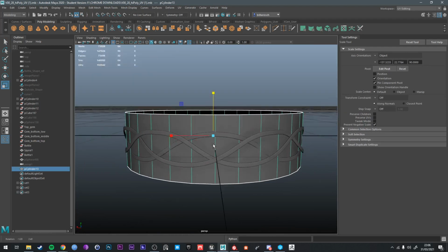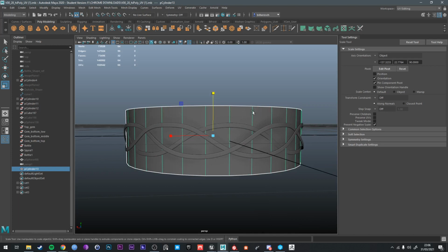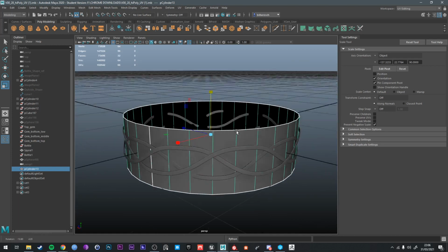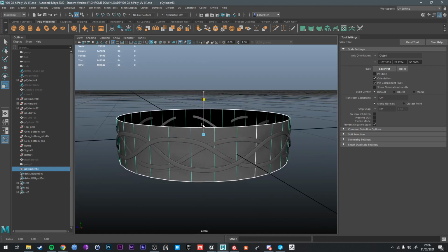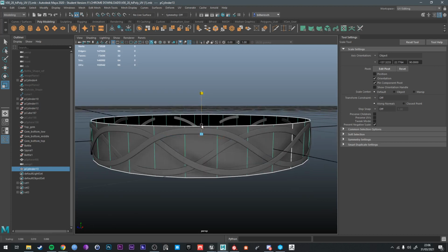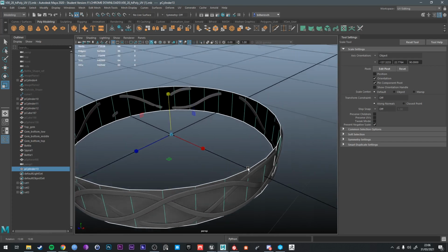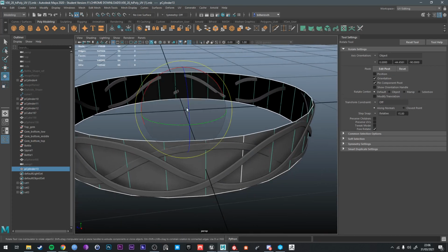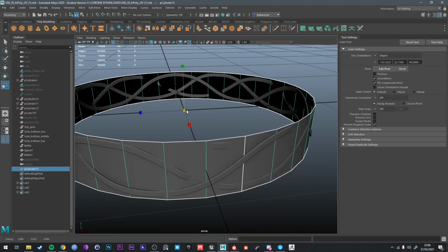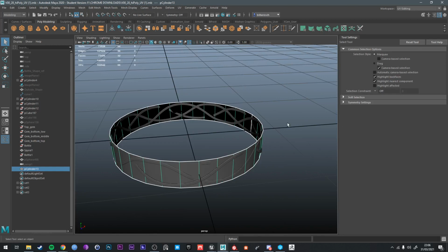So as a result, the more wasted space, i.e. the more translucent parts you have, the more expensive the model is to render. So in this case, we want to bring it as close as we can to the edge, leaving a little bit of gap just so we can make sure the bake comes out properly. And I'm going to scale this so it's kind of central.